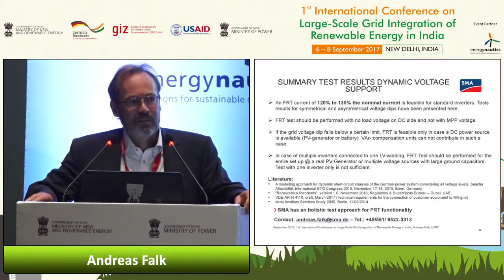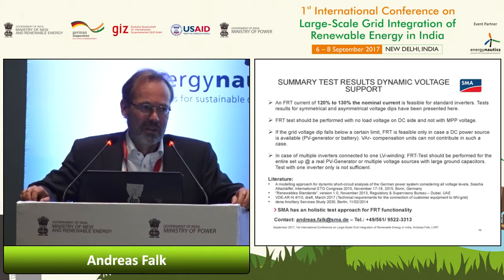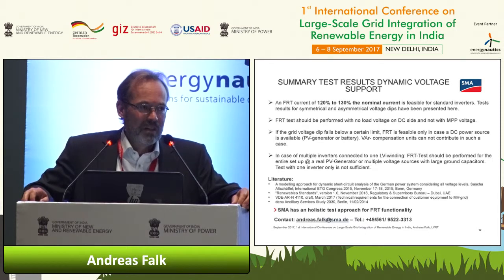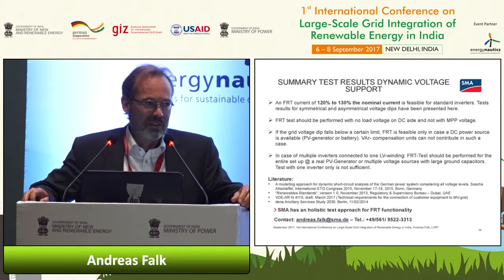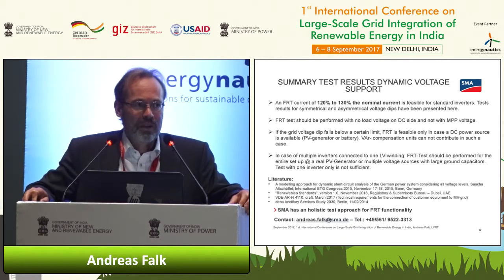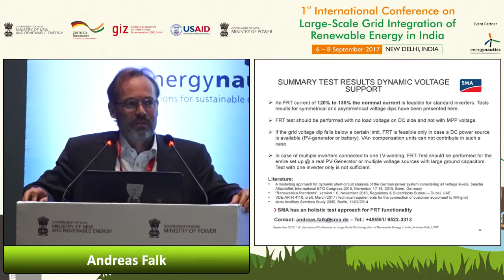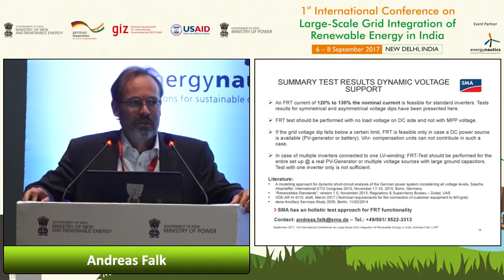It is not realistic to test it at every site. That is not economic. You have to specify a type test that considers the circumstances you have at site. That is very important. If you do not, maybe you have the effect that FRT is working in the lab and is not working in the field, and that is a pity because your grid is not supported.